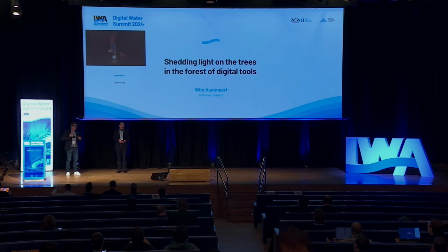Yeah, what I see when I especially look at the last 1 to 2 years, this means after a couple of years where we had first digital twin applications at treatment sites, for example, some leading utilities and academics start concluding that hybrid models are extremely promising for the treatment sites. And right now we see an enormous increase in applications there. So this means you apply a mechanistic model. We prefer the core to be mechanistic because that makes it explainable.